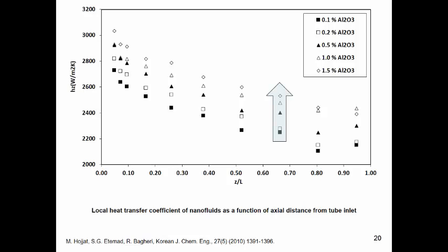The local heat transfer coefficient is directly proportional to the thermal conductivity of the fluid and inversely proportional to the boundary layer thickness. This means that the enhancement of thermal conductivity of nanofluids and/or decreasing the thermal boundary layer thickness increases the heat transfer coefficient. As mentioned, the enhancement of heat transfer coefficient of nanofluid is more than the effect of improving the thermal conductivity, which may be the result of reducing the nanofluid thermal boundary layer thickness.